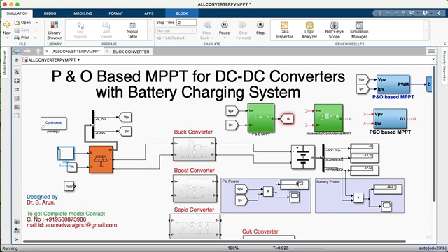I already mentioned it reaches 852.3 watts at a voltage of 58 volts. We can see the voltage gradually increasing from 819 to 824, 831, and it reaches 852.3. This is the PV power, and this is the battery power. You can see here the battery current is negative, which means the battery is charging. We can see the simulation runtime nearly reaches 0.0072 only.